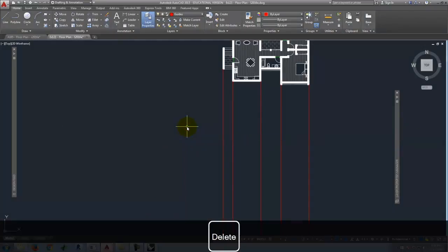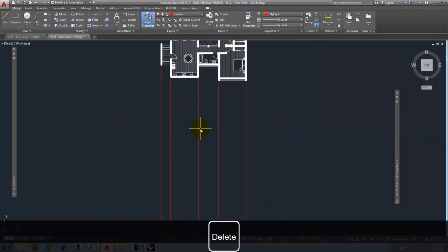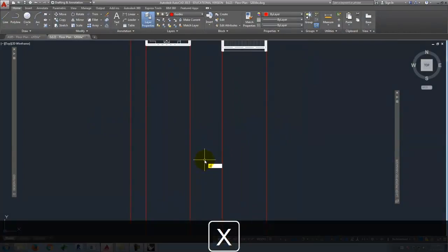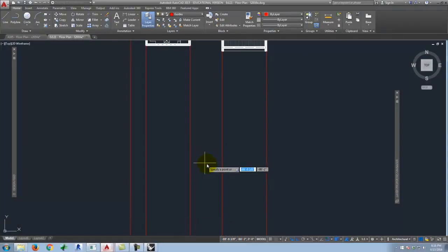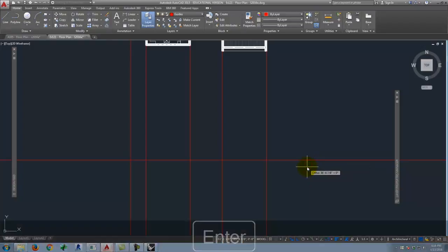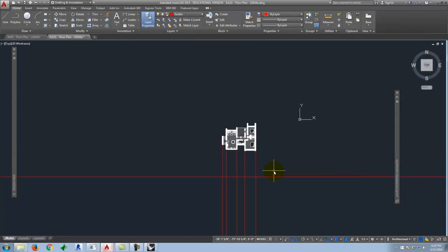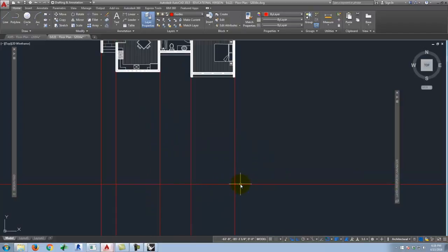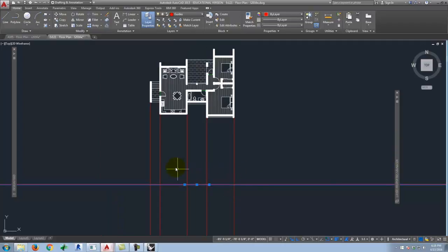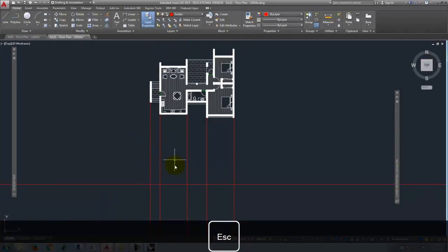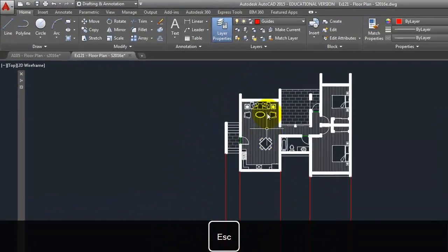The other type of construction line or guideline that you may want to use is called an X-line. And what an X-line does is it goes in both directions rather than just one. So I click a place where I want to start, and I move to one side or the other, and you see that this now goes in both directions in an infinite manner. Okay, so I'm using that to my advantage. Okay, so we'll assume for the moment that this is the interior floor level of the building. So knowing that, I can start to draw out the general boxes of this particular building.